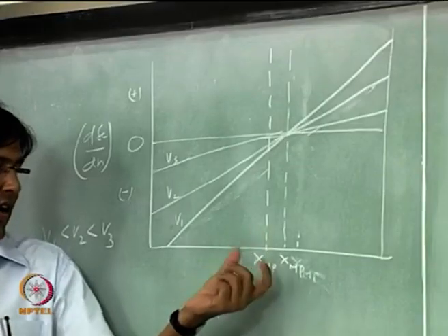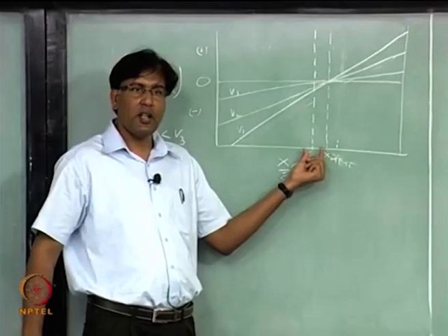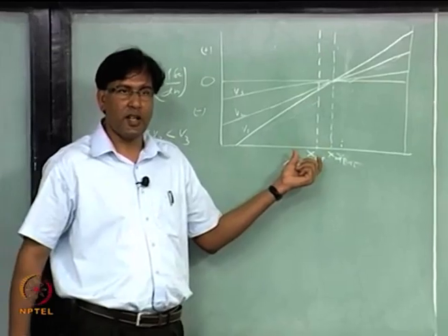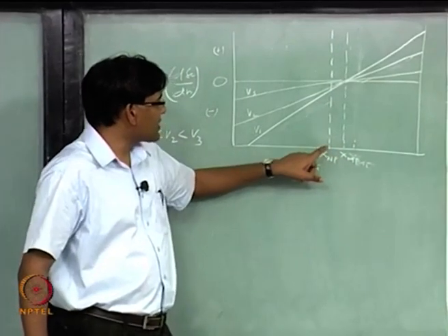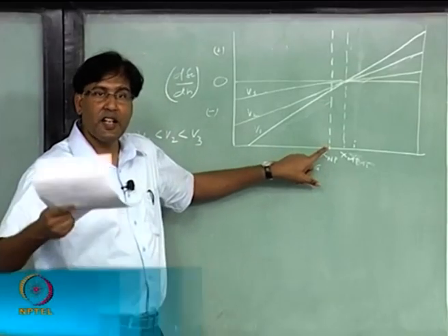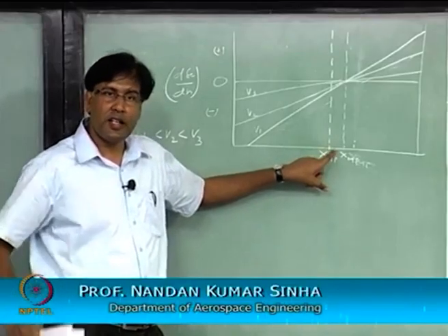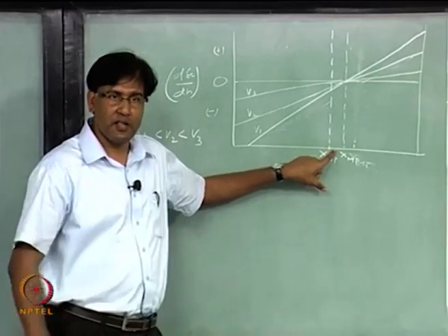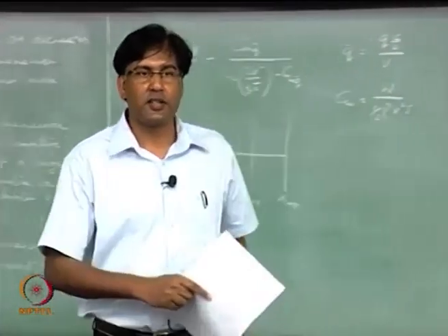What it is all telling you is that you have this margin, which is the maneuver margin, right. So, your aircraft can be marginally stable, it can lie very close to this XNP, or marginally unstable, when it is going to cross this XNP, it can still maneuver, and it will be a stable maneuver, it can still have a stable maneuver,